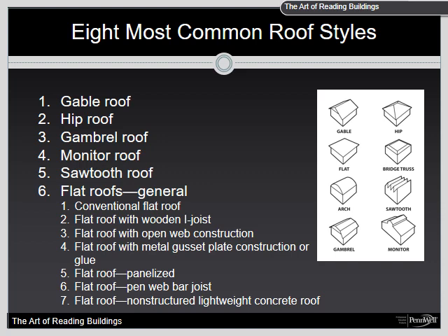Conventional flat roofs. A true flat roof has a pitch angle between 0 and 10 degrees, with a minimum of 6 degrees recommended for drainage. Wood rafters or joists of various sizes are usually laid across the outside wall. However, in some cases, rafters may also be suspended by metal hangers.